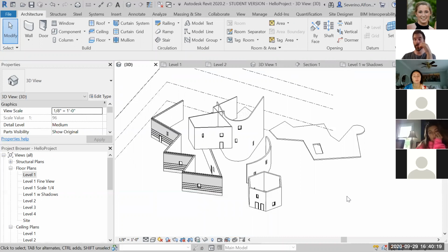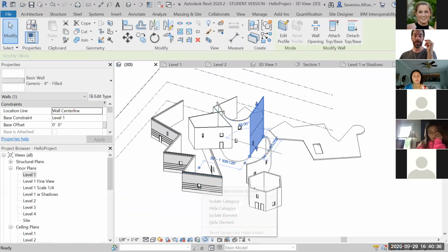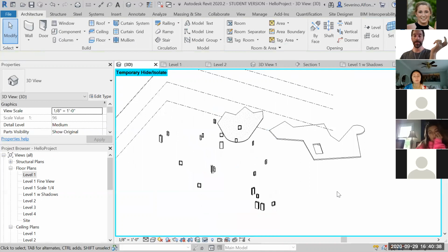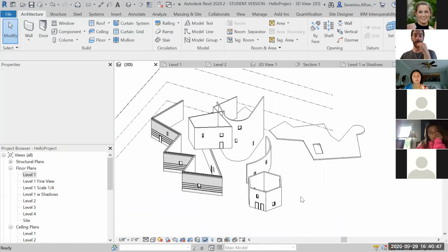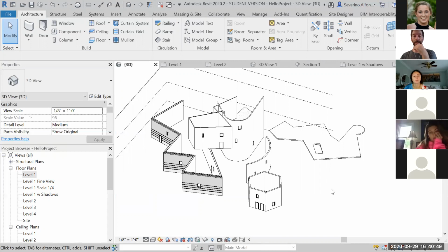Again, glasses are temporary. You can think of it as reading. You need glasses for reading or for driving or going to the cinema. You put them on only then, but you take them off afterwards. So it's a fast way of working with hiding and unhiding, the glasses. It also has a feature of hide category. And again, a cyan frame. I said magenta, sorry, cyan frame. That means that, again, it's temporary, reset afterwards, after you're done with something.